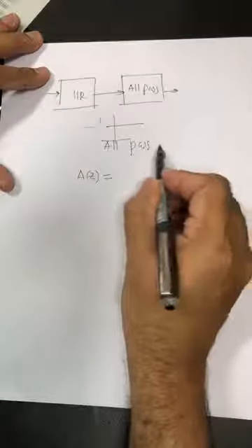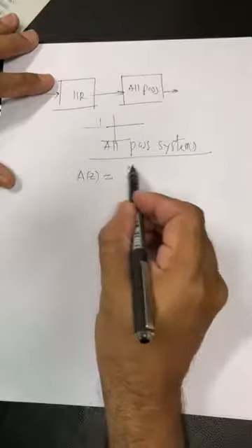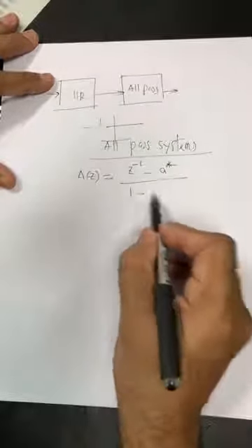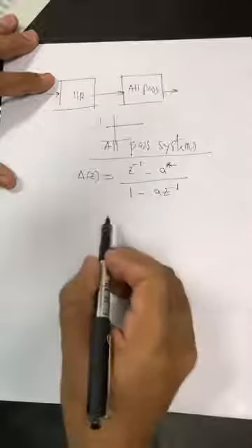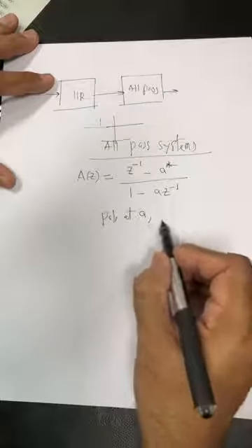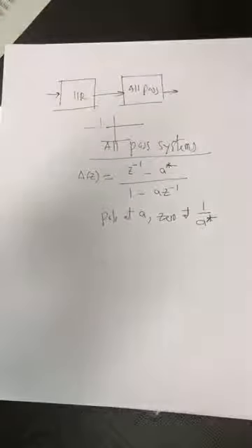They seem useless, right? They sound useless. They are not going to change the frequency content. What is the use of these filters? The use of these filters is as phase compensators. For every zero there is a balancing pole. So if it has a pole at A, then it has a zero at 1 over A in magnitude, to make sure that it is cancelling the effect of the pole on the magnitudes of the frequencies. And then it has even higher order forms as well.